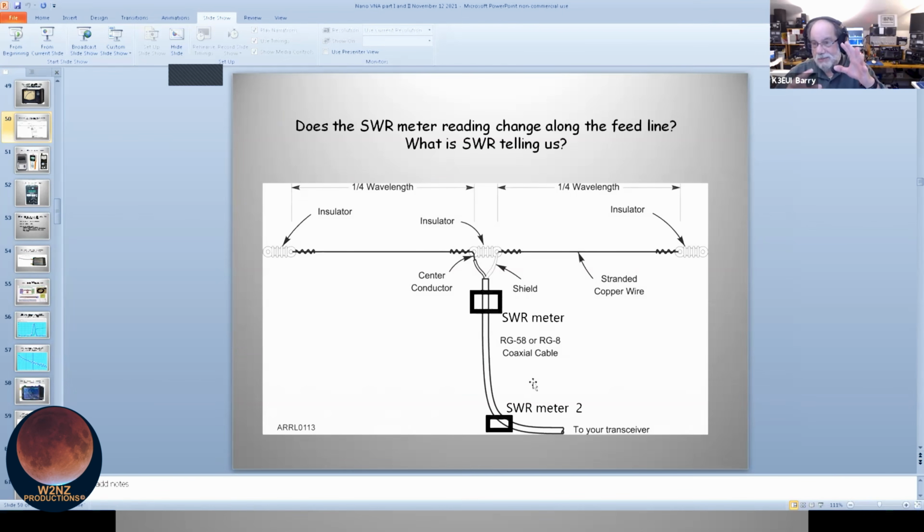Because often on a J-pole, you get reverse currents because you're essentially feeding an antenna that ought to have a choke or a balun next to the feed line antenna combination. So in 2 out of 2 cases, I was right. I said, well, you also might get some problems in your shack with the RF coming back down. Sometimes you touch a microphone, you get a little shock. Anyway, you don't want RF in the shack. But an SWR meter tells you very limited information, whether it's up at the antenna or down in your shack. It's better than nothing, perhaps, but it doesn't tell me anything like a Nano VNA.